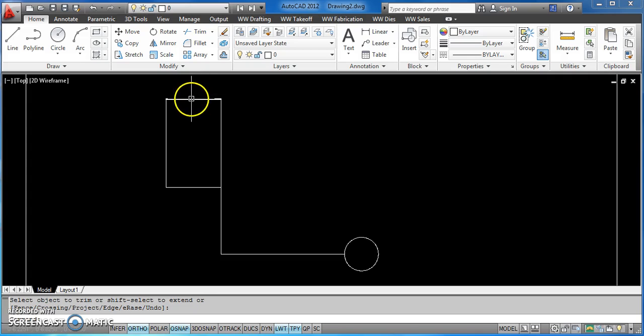Now in both those cases, the line extended beyond the cutting plane, but in this case I'm going to demonstrate that I'm going to use this line to trim this longer line, even though it just has an intersection point and it does not cross all the way through.